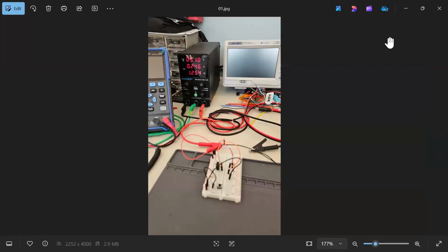And as I said, I want to breadboard this first. So what I've done is I've breadboarded the main circuit without the PIC microcontroller here. So you can see that there's a resistor network here. We have the power MOSFET here. And then I have a manual push button that will turn on the transistor, turn on the MOSFET, and make the circuit go to full power.